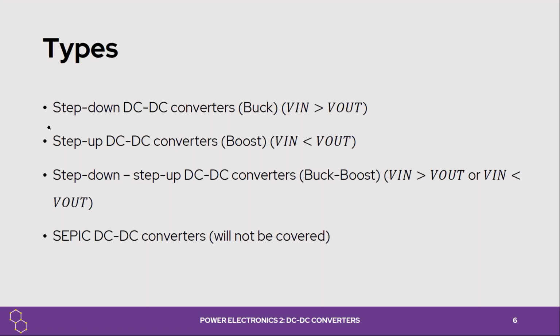This helps us a lot in boosting the voltage when needed for feeding DC motors that need larger voltage than the battery. So we feed the step up DC to DC converter from the battery, and we boost the battery voltage output to feed it to, say, a DC motor.